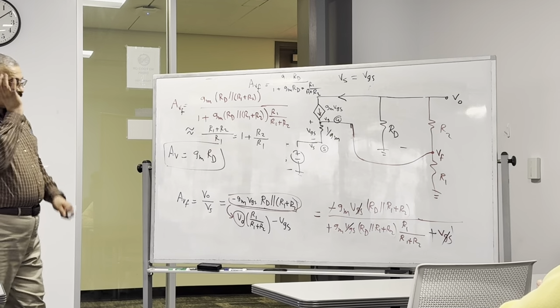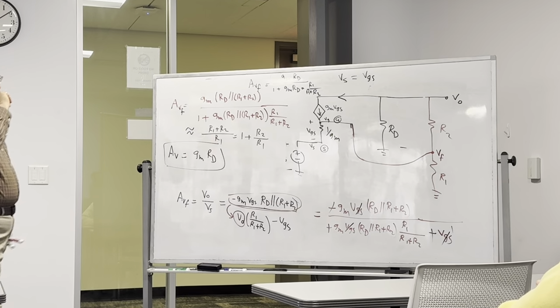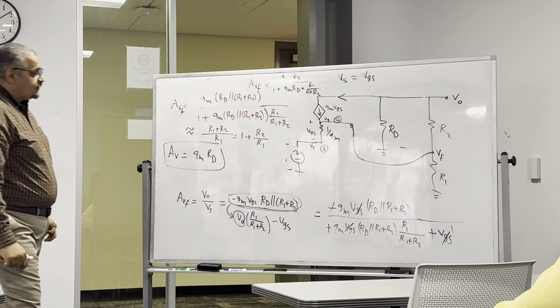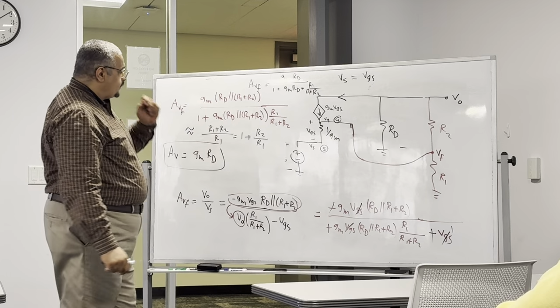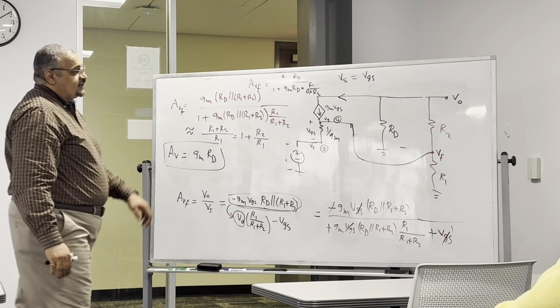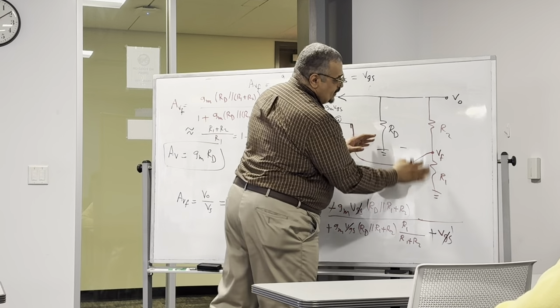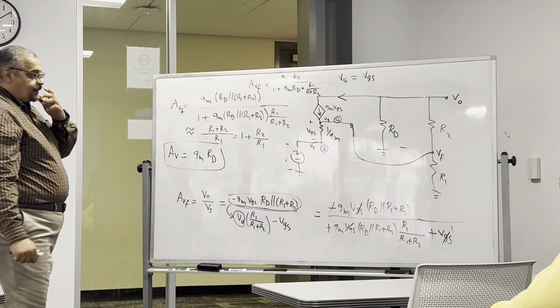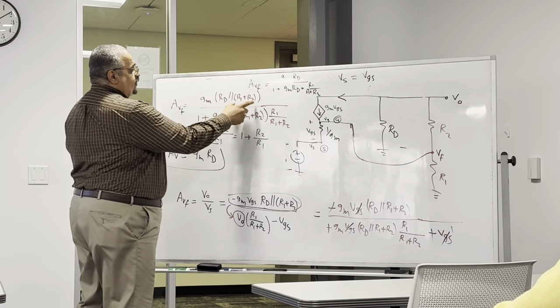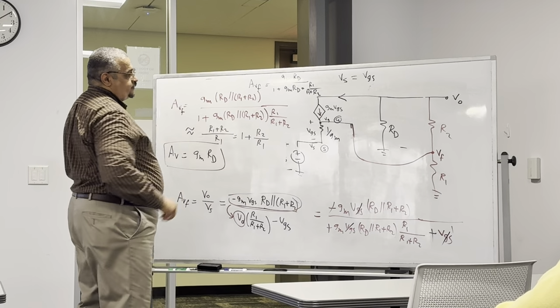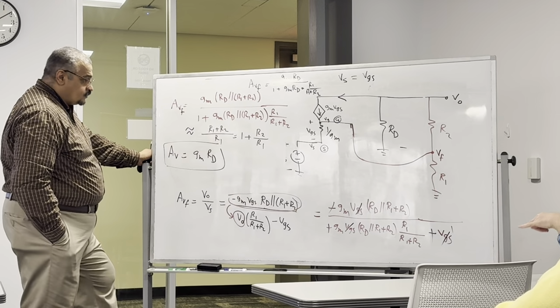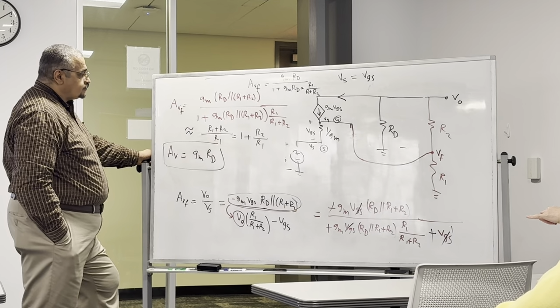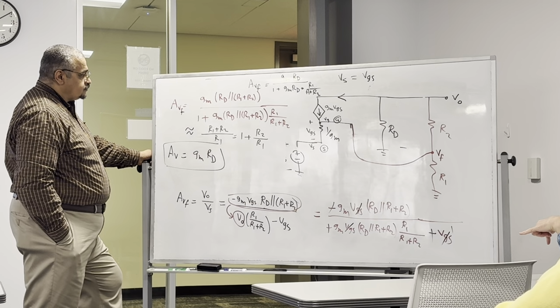In practice, you probably just adjust RD to account for the feedback, right? So RD in parallel with R1 plus R2. We need to adjust RD to make sure that R1 and R2 in series are much larger than RD. I was just thinking that once you take them in parallel, you would end up with the same impedance to ground.